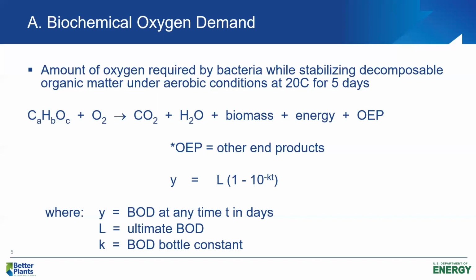But anyway, we mathematically describe the BOD at any time as equal to L, the ultimate BOD, or long-term BOD, times 1 minus 10 to the minus KT. So what this equation does, again, if we were to use BOD 5, then T would be 5. It allows you to calculate BOD at any time if you know the ultimate BOD.